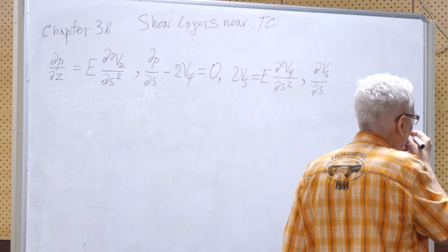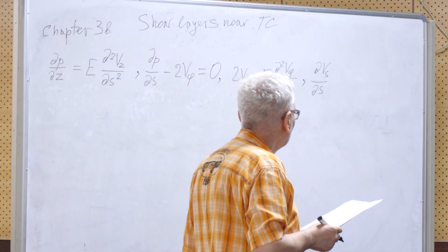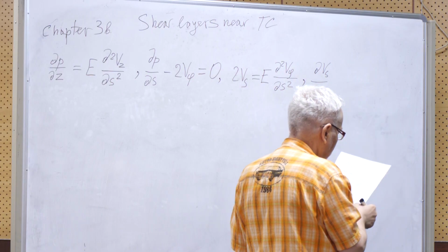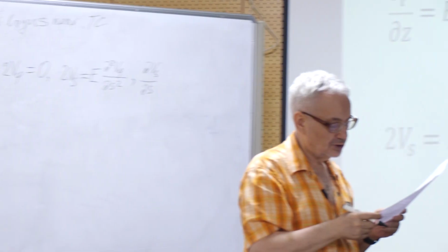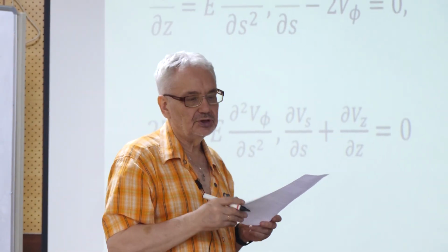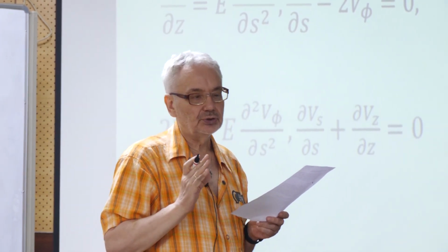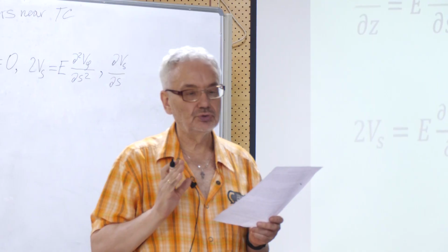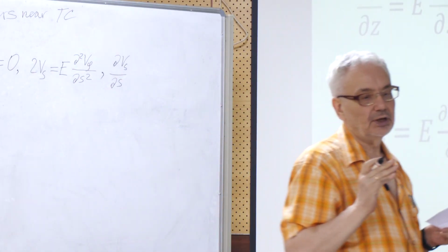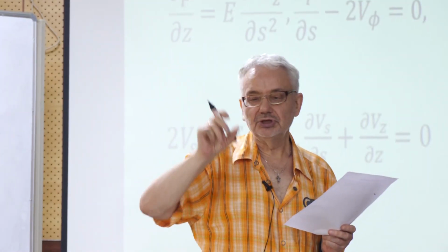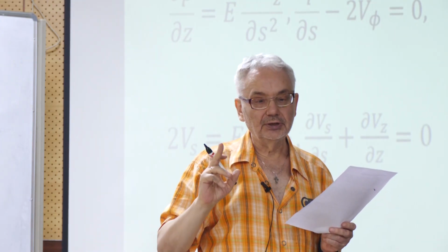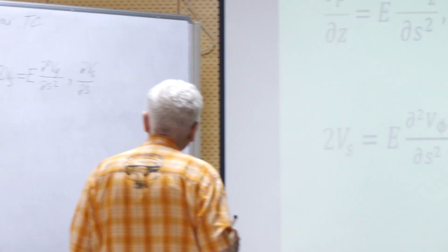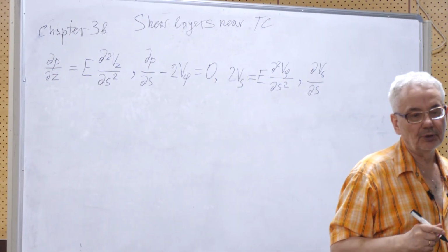So in fact, for this divergence we have first of all these derivatives, and also because there is not so big change in the z direction. So in this case, we have the velocity which is straight from the shear layer. There is a shear layer, so it's very difficult to penetrate the shear layer from one part to another part. But it's quite easy to go along the shear layer. So in the direction of the axis of rotation, the shear layer is sort of a layer. Parallel to the layer itself, it's quite easy hydrodynamically for the velocity to go. So that component of velocity is rather important, more important than other components, because in the shear layer we have